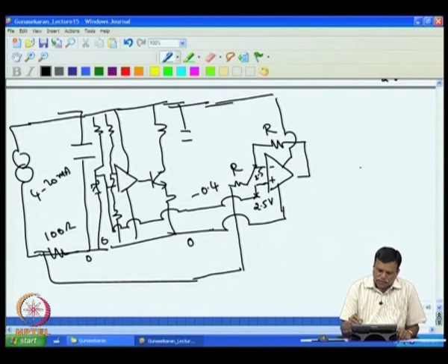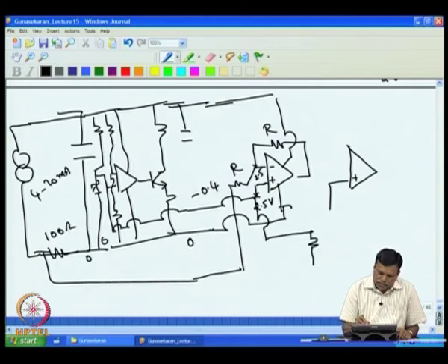Then what we do is we will compare this output voltage with the reference voltage. So, if this reference is given to a positive, which can be this itself. So, I can have a reference, that is, this is our ground. So, I connect this to ground and then I can set this whatever value I want, and then this voltage, if it is very high, I can put a divider and suitably scale it down such that it matches with the reference. Then this can be used to